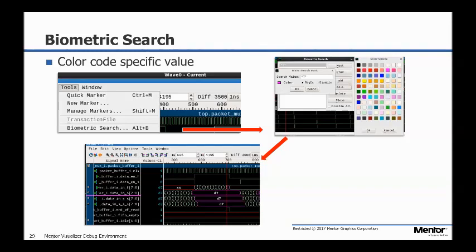Another thing that's useful is if you're tracing sequences, maybe you're tracing a packet of data and there's a unique packet ID in there. You can put that packet ID in the enumerated search, and then you can see how that packet is flowing through your system.